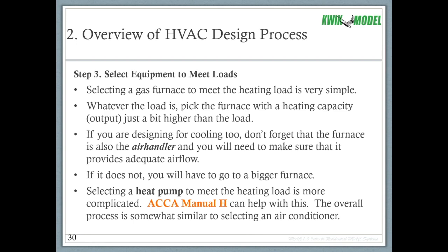The output capacity is relatively not sensitive to variations in design conditions. One of the things that you do have to adjust furnace output capacity based on is altitude. As you go up higher in altitude, the capacity is a little less because the density of the air is different. But other than that, furnaces are pretty much dumb beasts. You have a load and you pick a furnace that'll give you a load slightly higher than that.